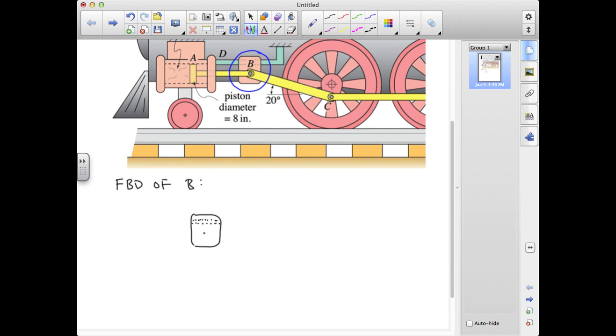We're going to have three forces acting on the crosshead. The first force will be the compressive force from the piston. We're going to be able to calculate that. I'm going to write that as FAB. That's shown pushing into the joint at B because member AB will be in compression. It will turn out that member BC will have to counteract that, so I will also show member BC as being in compression, and making a 20-degree angle with the horizontal. And finally, because the guide is frictionless, it will have a reaction force between the crosshead plate and the guide that's purely normal, and that will also be in compression in order to counteract the vertical component of BC. So I'll draw that as FDE.